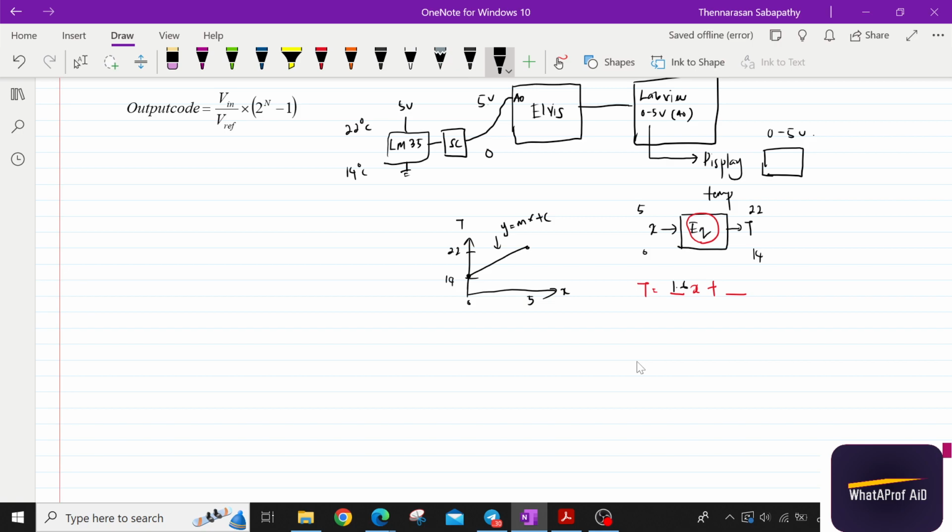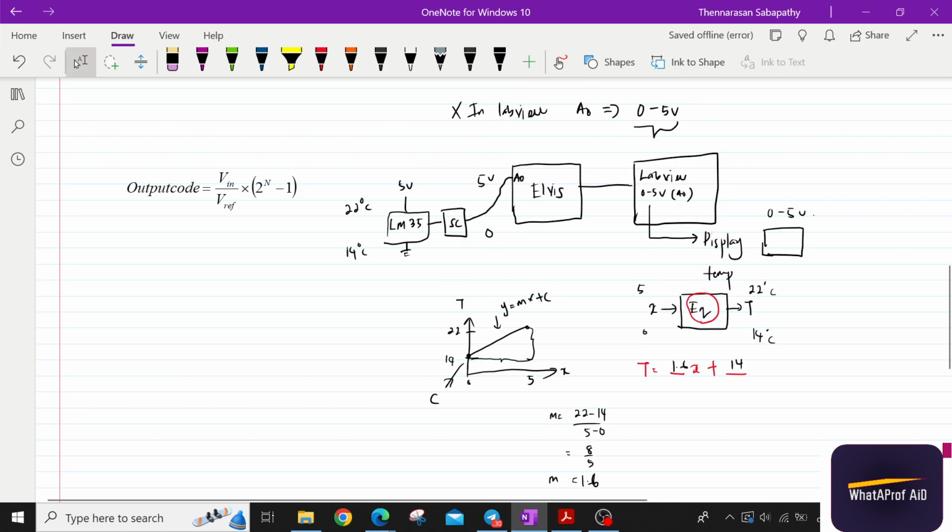This is actually linear, but if it is a non-linear equation, you have to translate in terms of the log. Like the NTC, they have one equation, I forgot the name. But still, because we have a very narrow temperature range, you can still assume linear if you want. It's not so accurate for an NTC, but still better than just multiplying with 10 or 15 or anything.